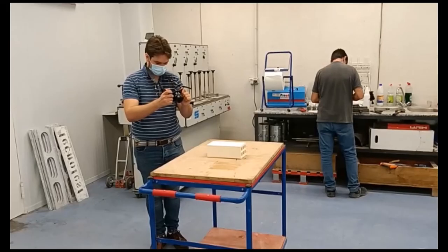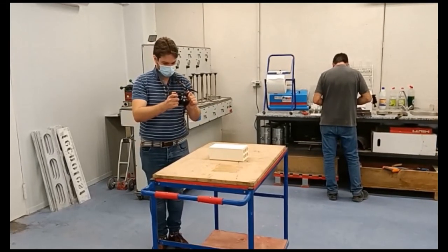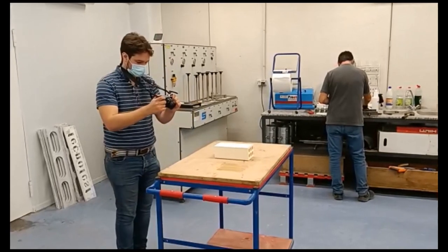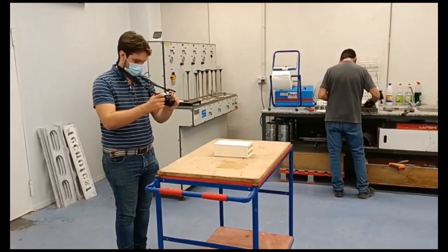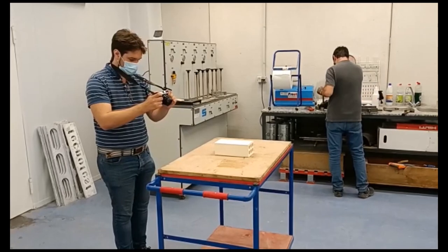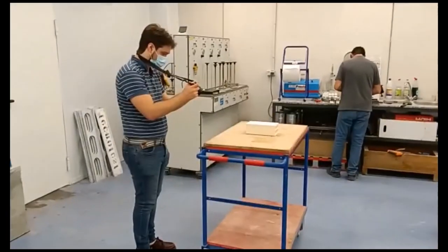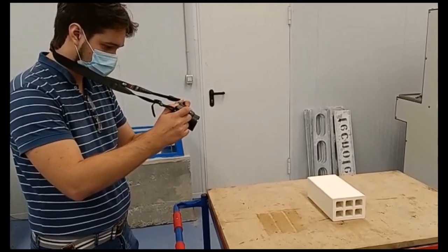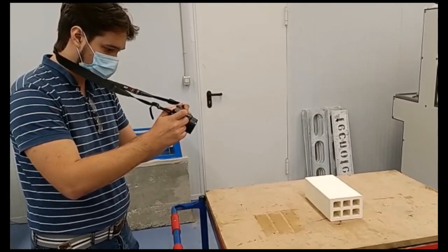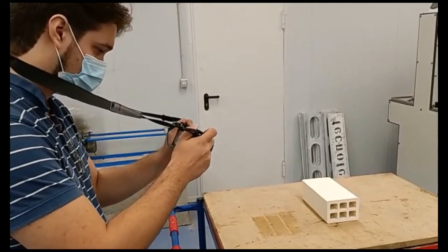Object Capture. Practical example of object photogrammetry with a camera. In this exercise, we will proceed to photographically capture an object with a camera, taking 360 degrees photographs of it and processing this data using the Reality Capture program, from which we will obtain a point cloud and a polygonal mesh. Data capture. The object to be captured must be completely still while the technician makes enveloping movements around it and takes pictures. It is advisable to take one photographic capture per step around the object.